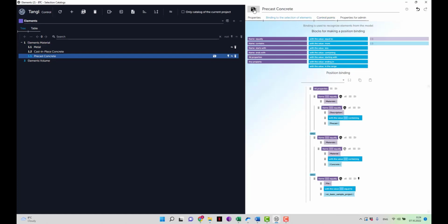And now we're almost ready to make our checks. But the last thing that we need to do is to make every binding quick. You can see the bolt icon at every position. It means that there is a quick binding at this position. Quick binding is that binding that uses the equals function and not the contains function and so on. That speeds up the search and saves the resources of the service. So you should necessarily use these quick bindings to make your checks.